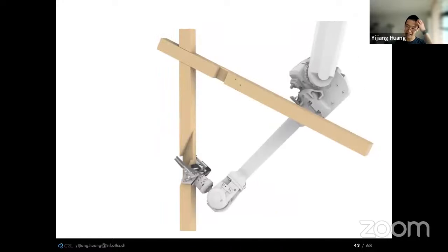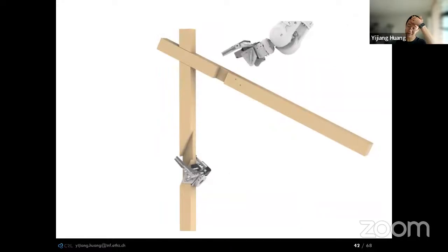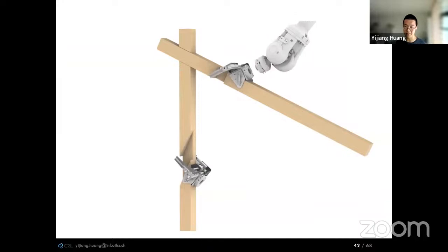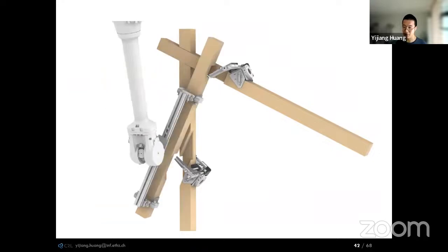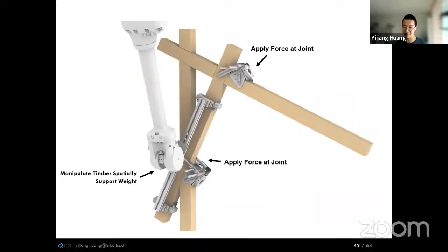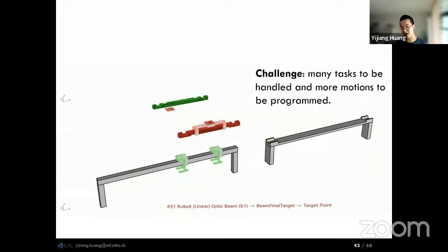So Victor had the idea of designing remotely controlled clamps that can be mounted on the timber and can generate a large amount of pulling force. Then the robot arm can simultaneously push the timber elements into the joint together with the clamps. This will overcome the large amount of friction force required by those integral timber joints. And with this concept, we can already start to organize robot actions and visualize the process here.